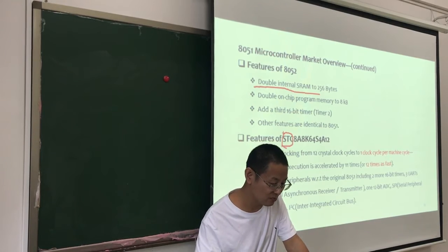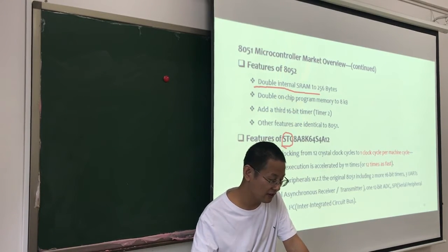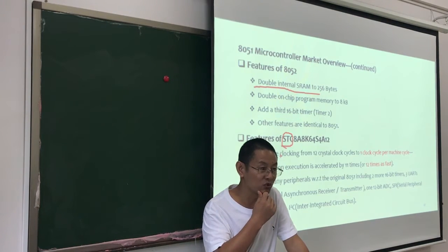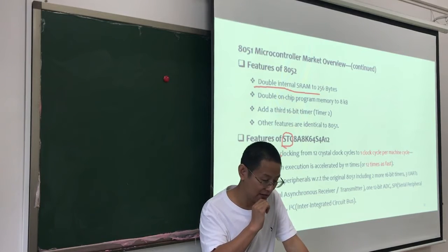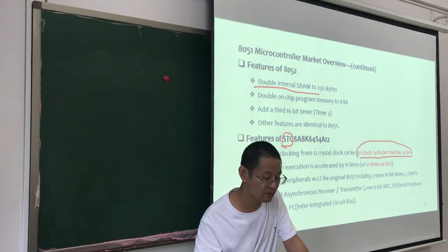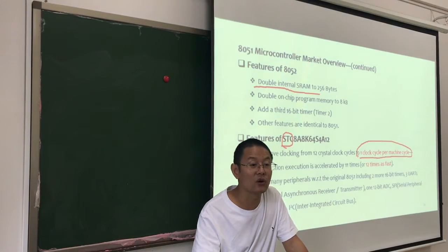Just know that this STC microcontroller is the same as the 8051, but something is different. It's 1 clock cycle per machine cycle. It means that 1 clock cycle is 1 machine cycle.